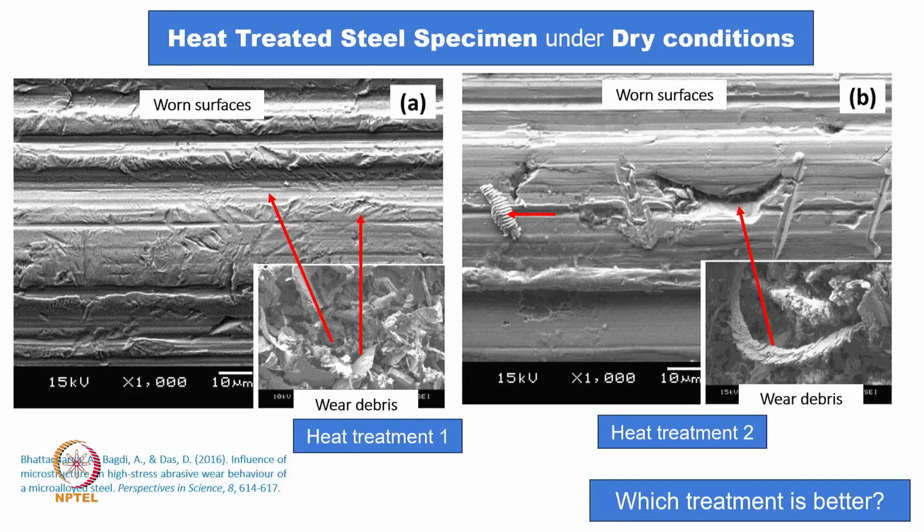So, we can say that by observing the wear debris, we can judge the effective loading condition or the operating condition, and we can really take remedial action on that. Now, we will just cover a couple of examples in that. Let us think about the correlation between the wear debris and the surface, and that has been shown in this case, and particularly in this case we are using the word dry condition. What is the importance of dry condition? Adhesion will also be there. If I make it a lubricated condition, quite possibly adhesion will be removed. So, in this case we want to really look at what the correlation is, how the debris will come out, and what the relation is between the surface and the wear debris.